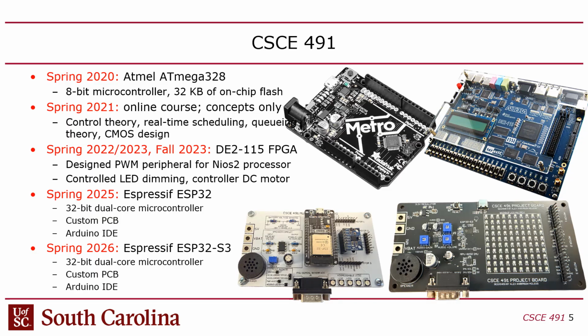So this is the new board, and this is actually Rev 1. Alex found some bugs that we're going to fix, and we're going to get another batch of these made, and this is the board we'll use. That make sense? One other change I made is we switched from micro USB to USB-C because some people were having the USB ports come right off the board last year. So I switched to USB-C, and that should help as well. These modules had a really delicate USB connector.